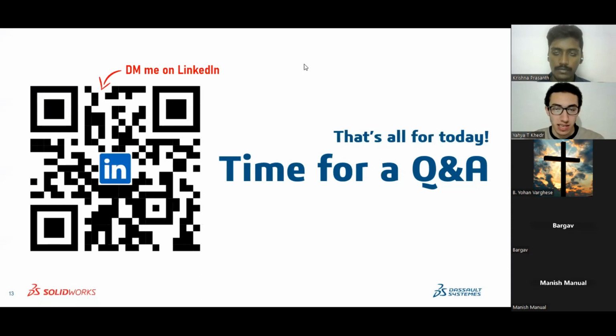In that case, you might need to either use a macro to edit all the dimensions at once, or use the scale command to scale down your model. But the issue is that your model isn't really parametric anymore, because if you edit any dimension before the scale command, you get the dimensions in their previous values, but after the scale command, they're in the new values. It's probably going to be a bit confusing, but if that's the only remedy you have instead of recreating the model, then of course, go for it.